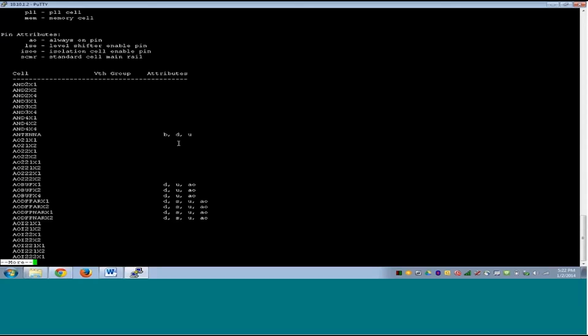Don't touch means that if this cell is already present in the design, so this cell could be present in the backend in the post layout, right? Because the layout engineer might have used it. If this is present, then don't touch it. Many people like to instantiate some technology dependent cells in their RTL.